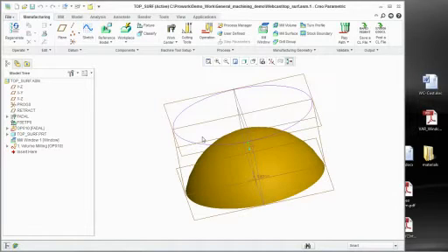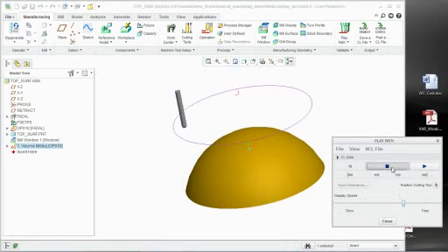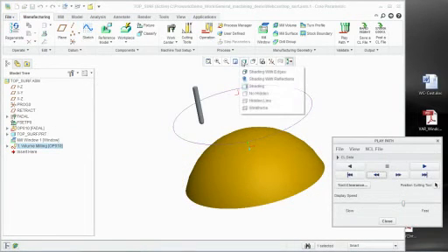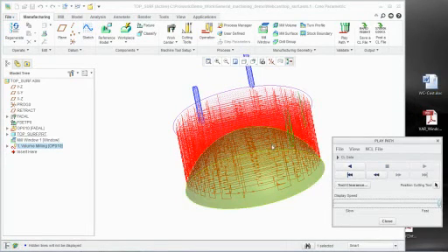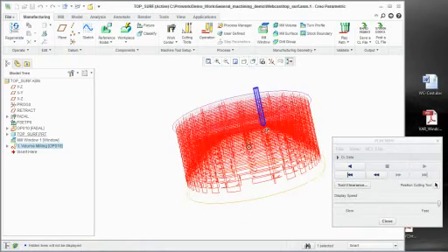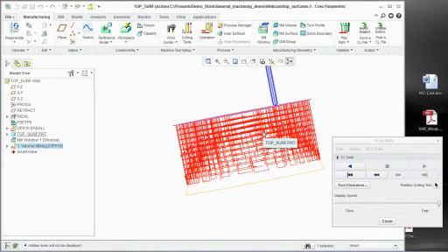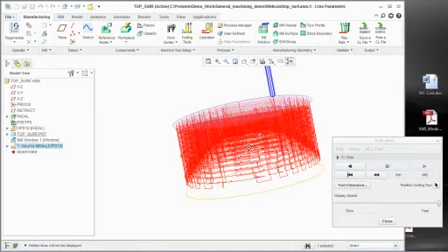All right. This one right here, what I wanted to show you is a typical voluming sequence that you would create. Hold on here, guys, so you can see this. This is a typical voluming sequence that you would create. And what you get here is a lot of airtime cutting if you are cutting castings. If you want to do voluming or hogging out type sequences, and you have just a casting or a half inch or a quarter inch worth of material, you do a lot of air cutting in these situations.